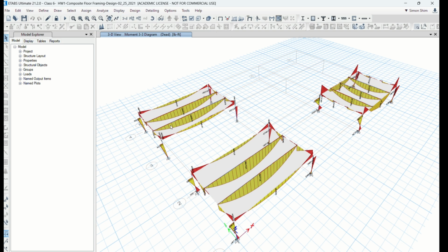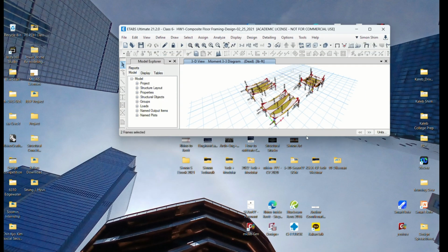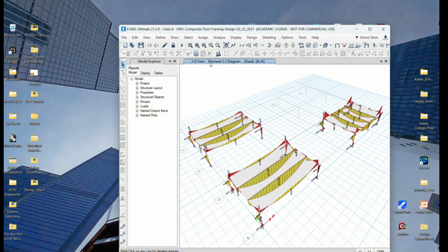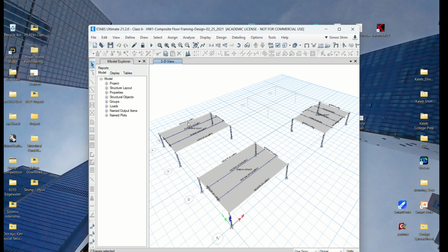But anyway, here assume that I double checked, right? Every shear force and moment diagram is right. Now, what do you need? You need to define that this is the composite beam module. You may have to define, okay, I'm going to use this beam. It's going to be simple. I select this, record model. Somehow they don't allow me to, okay. So I select these two beams as composite beams for this example.